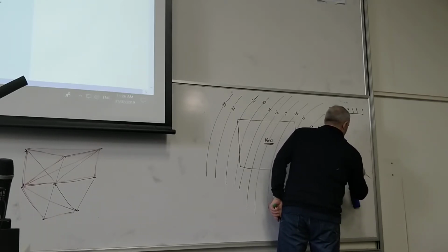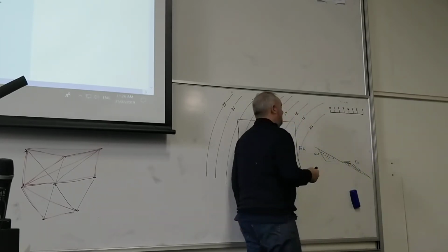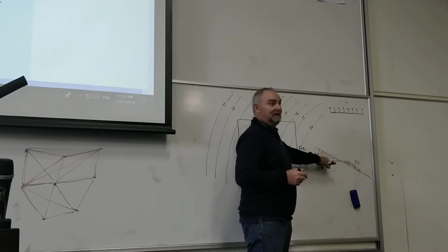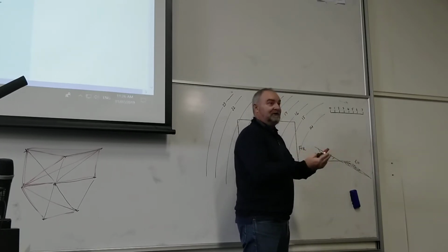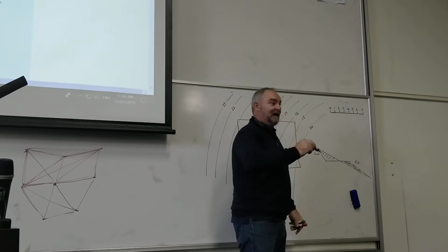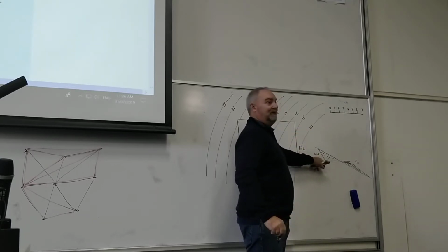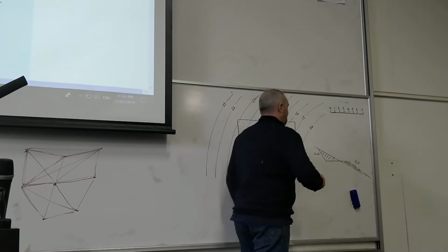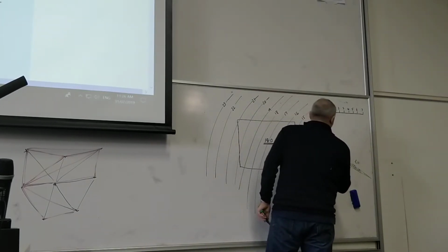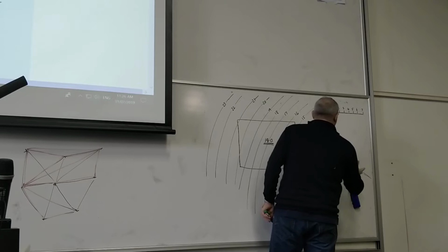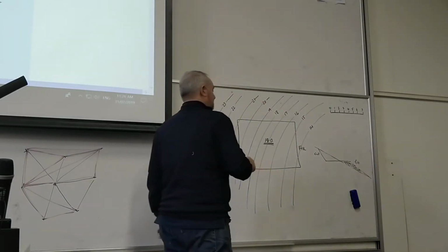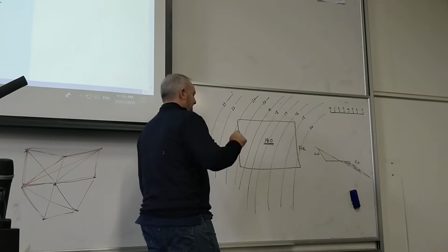Okay? For example, something like that might be good enough. And I'm sure you can be inventive on what you use here. That is actually for a building. So if you're sending in a set of drawings that's got buildings hatched like that, and then you do your long section with a hatch like that, it's kind of sending mixed messages. So, yeah. You will need a different type of hatch for cut and fill, so I'll let you come up with something that doesn't conflict with geological terms.